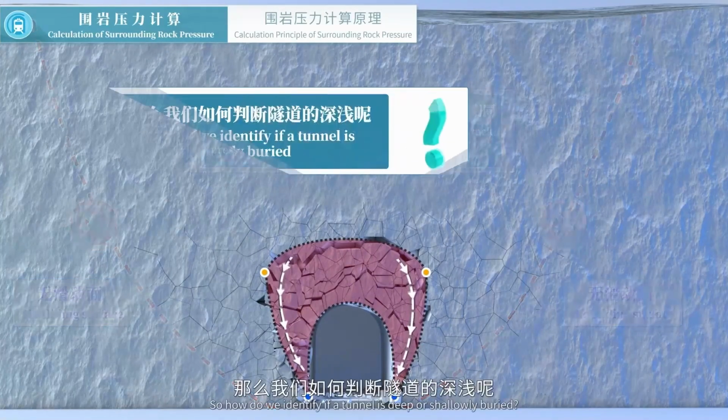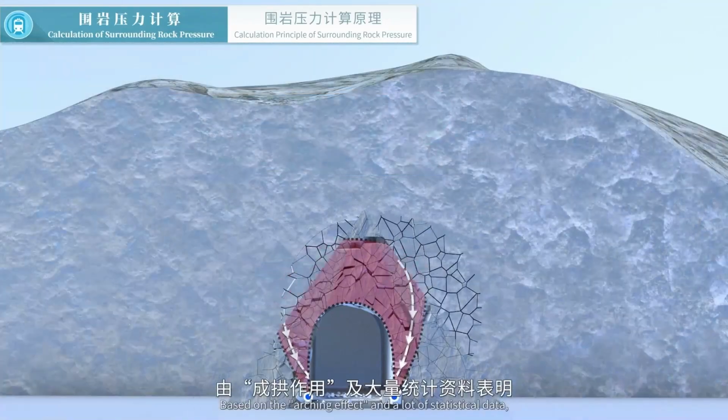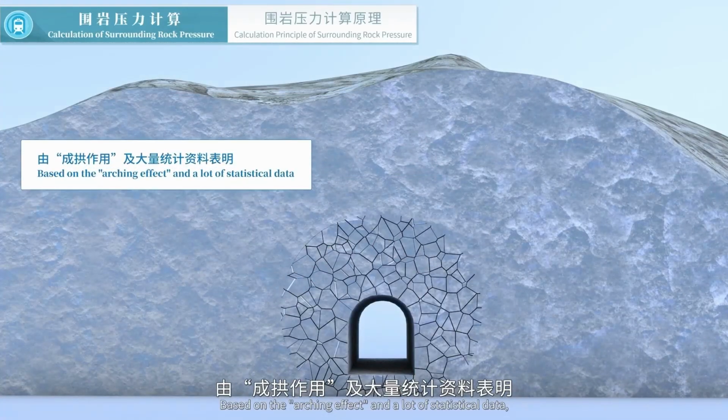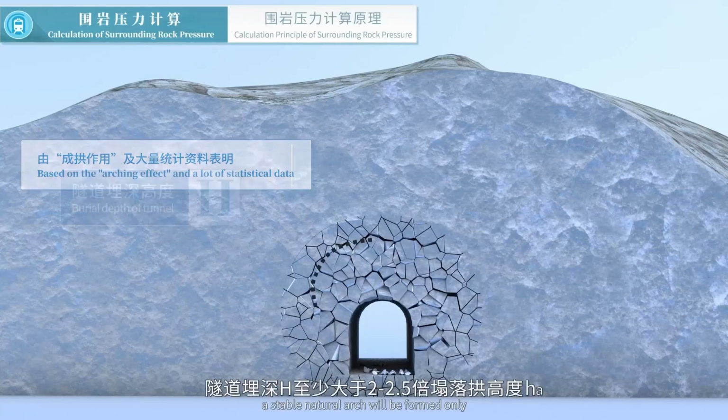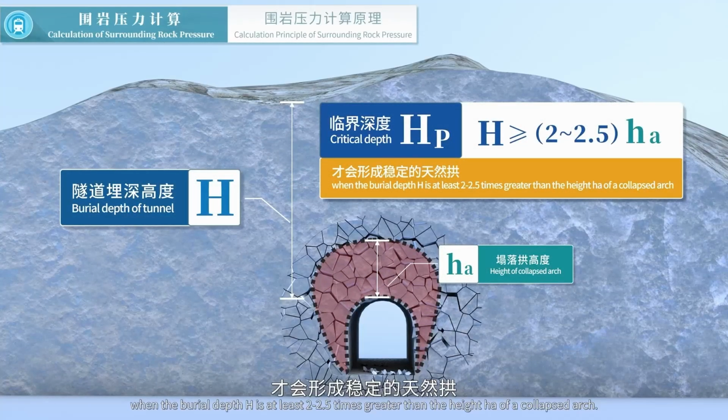So how do we identify if a tunnel is deep or shallowly buried? Based on the arching effect and a lot of statistical data, a stable natural arch will be formed only when the burial depth h is at least 2 to 2.5 times greater than the height ha of a collapsed arch. This critical depth is called HP.